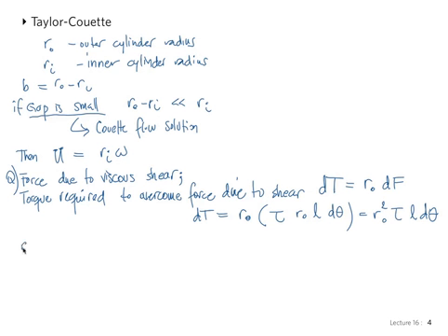So the total torque would be, yes? You have two terms for torque? It's a small differential of torque. I'm going to have to integrate. But then your tau over there is torque also? Tau is the shearing stress. If you recall your definition of viscosity, forgive me that these letters look similar. Tau is a Greek letter, our shearing stress, so mu du/dy.